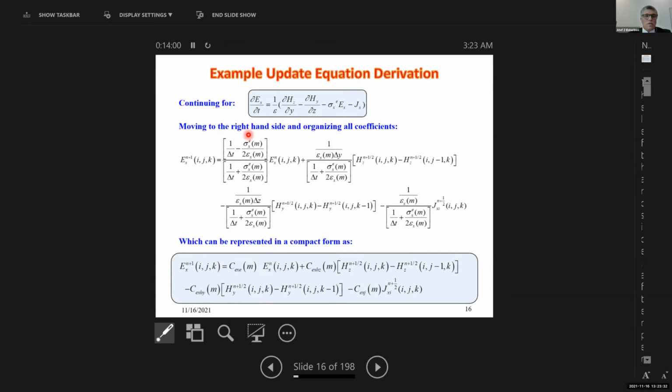And because we are going to execute this equation so many times, we evaluate all those coefficients one time before we do the time iteration, and we store them in 3-dimensional matrices like what you see here. The M here is an abbreviation of IJK, and we evaluate this matrix, this matrix, this matrix, this matrix once, and then repeatedly evaluate this equation so many times, 6 million times 1 million, so that we can get the solution for Ex.